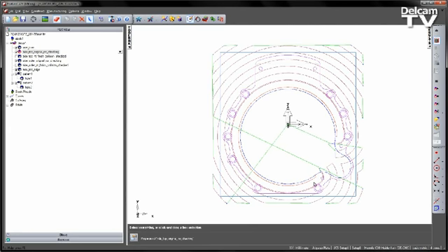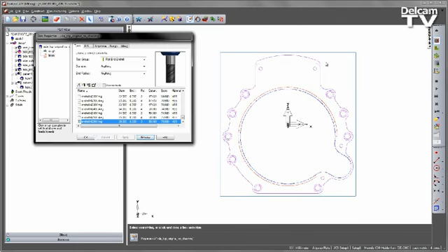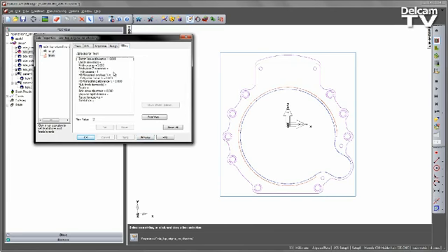So we can modify the way the tool moves in these regions by using some of the new high-speed machining options. In this case we go to the milling tab, and you'll notice you get a number of high-speed machining options, including the maximum tool overload, which will introduce trochoidal moves. We've got the profile corner percentage, which will introduce a rounding to the last profile. And we've also got the smoothing allowance, which will try and smooth out the toolpath as best it can using the raceline technology.